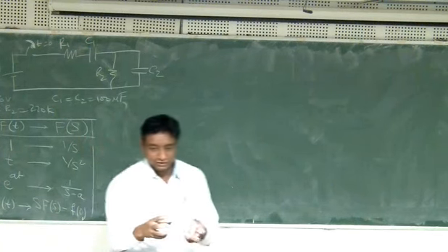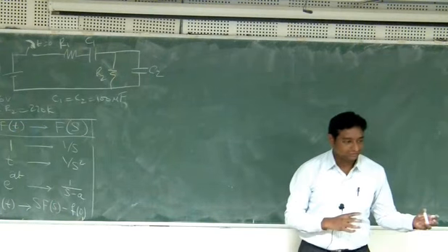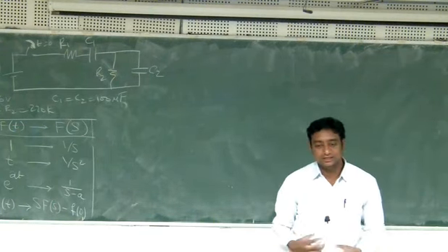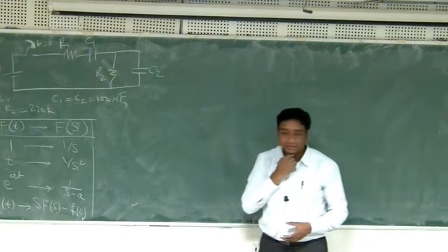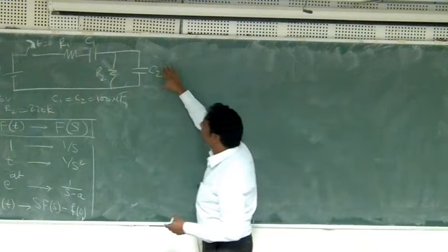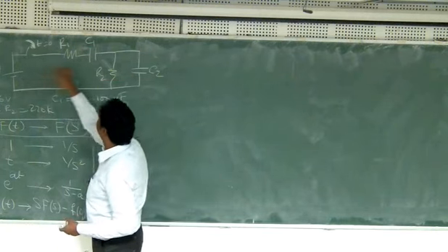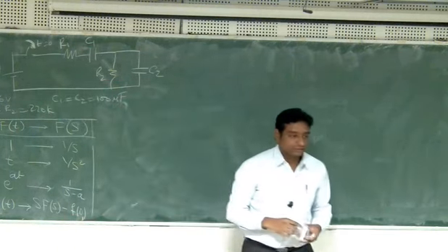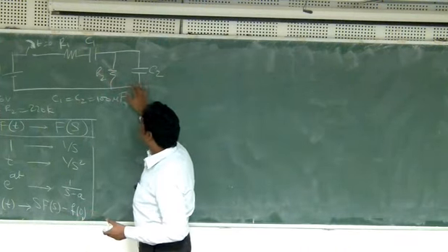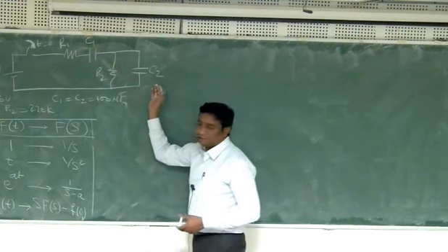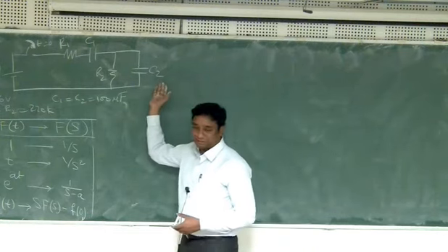We in fact connected the circuit and we noticed this thing. We have not taken exact time versus voltage values, but we just looked at the behavior of this circuit. What was noticed last time? We were mainly looking at VC2, and initially when I close the switch, both capacitors have 0 voltage at the beginning. It will start charging, and then after a while there is a discharging path for C2. So in steady state, after a long time, C2 will discharge and the voltage will become 0.